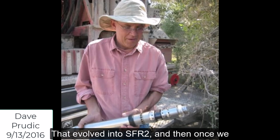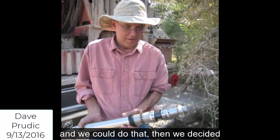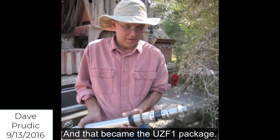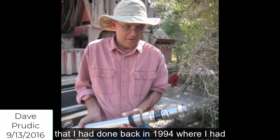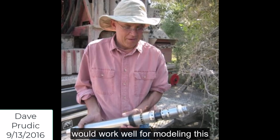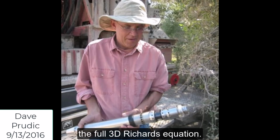So that evolved into SFR2, and then once we proved that was feasible and workable, we decided to do it over the entire domain, right? Didn't matter whether you were underneath a lake or underneath the stream or just at the end. And that became the UZF1 package. That was all from that original research that I had done back in 1994, where I had identified certain analytical equations that would work well for modeling this unsaturated flow without having to go into the full 3D Richards equation.